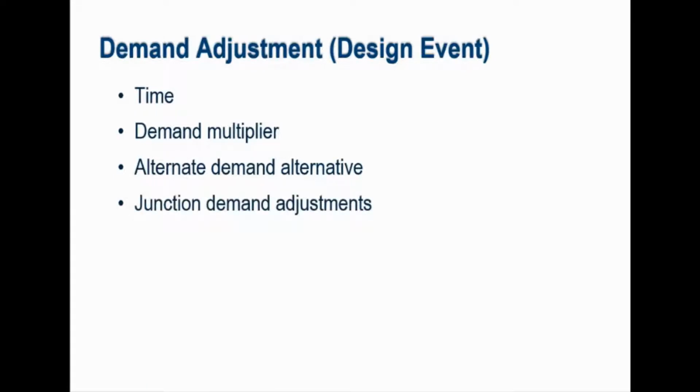If you have one node, maybe you'd like to adjust to correspond to fire flow, you can directly input that too. So you can make specific selections of changes inside the Darwin study. Maybe it's demands for a hospital. You can put that particular flow that's needed or something there, or pressure.